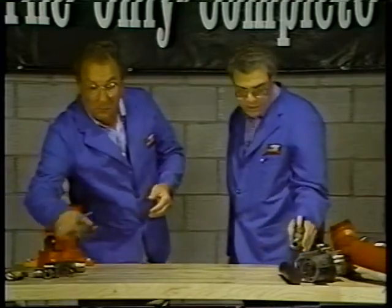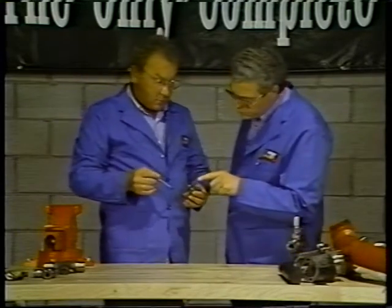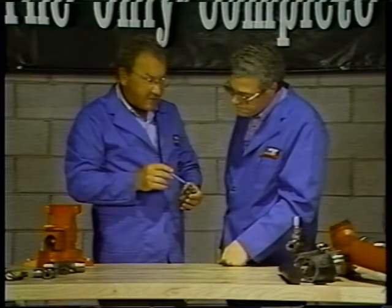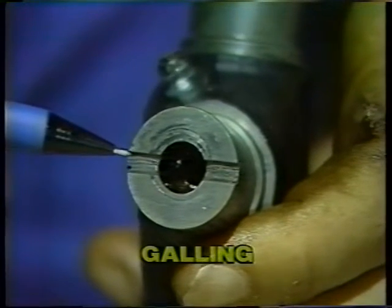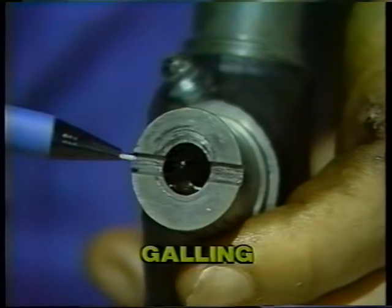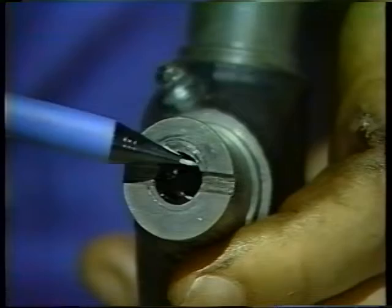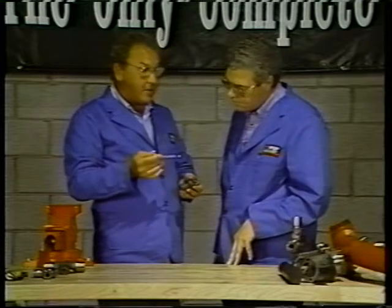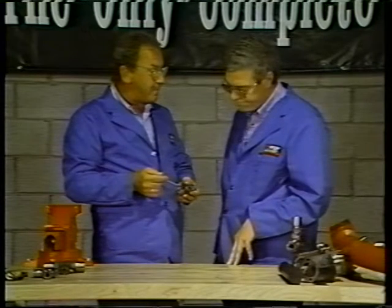Let's take a look at another U-joint failure. This one seems to show a lot of wear on the end face of the cross. That's caused by excess pressure and a scrubbing action between the thrust surfaces of the cross and the bearing cap. It's called galling, and in severe cases, the cross and the bearing cap may weld together. That can't be very good for the system, can it? It isn't. In fact, when this welding occurs, it can contaminate the lube, which leads to additional problems.